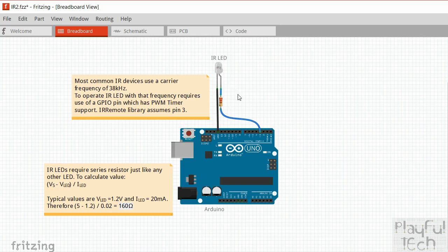Like I said, if you want to extend the distance through which this transmitter is going to work, well, to do that you need to make the LED flash brighter, and you might want to look at getting a higher intensity LED to do so. And there are plenty available. If you do that, know that you will probably have to recalculate the resistor value to go with it.